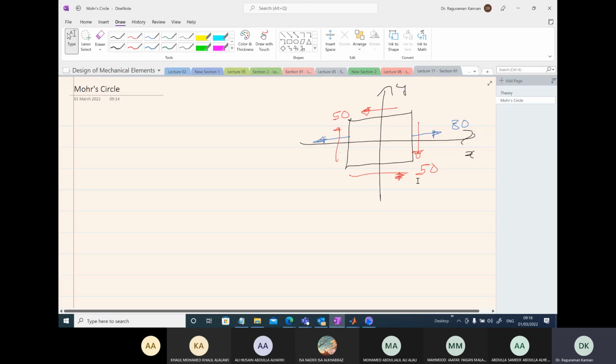When you are given a stress element like this, first we need to write what is the stress matrix with the correct signs. So let me draw the normals. Normal, positive here, normal, negative here. Here we have normal, negative, normal, positive.